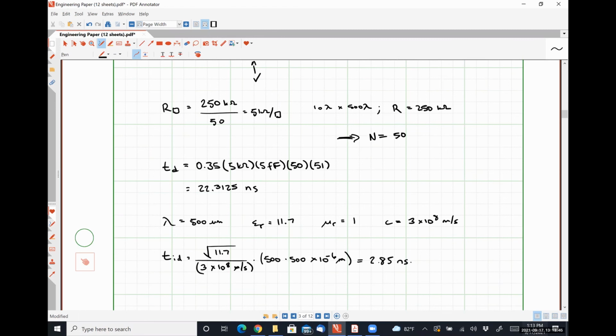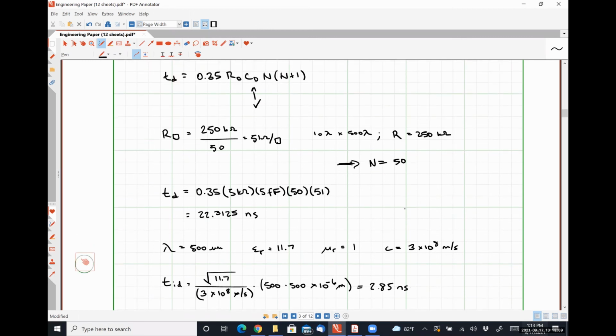We're trying to send this signal through a 10-inch distance on a chip, and the intrinsic delay time would be less than 3 nanoseconds. So even in this case, where we're sending it over a hugely long distance, the RC delay time is still what governs how long it takes the signal to propagate down the transmission line.